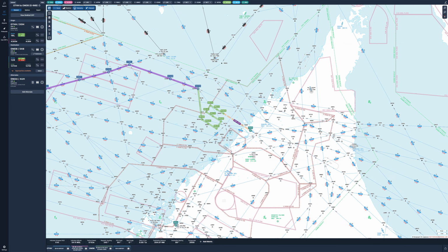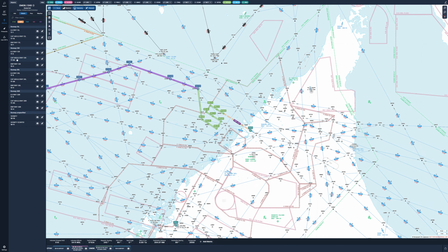So let's go over here and select the approach procedure. I will be using runway 12 right, and I can go for category 2 and 3 ILS runway. It's actually the precision. The most precise is category 3, then less is 2, and then 1. So there are different procedures that you have to follow. This plane is capable of carrying out the category 2 and category 3 approach, and during the approach, I will tell you what is the difference in the category 2 and 3.